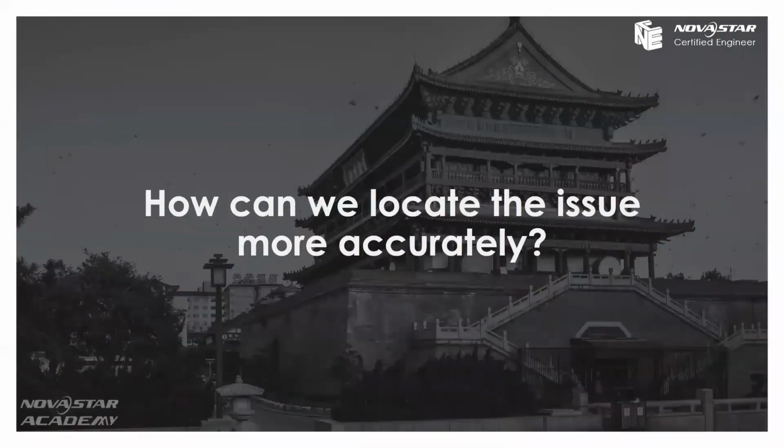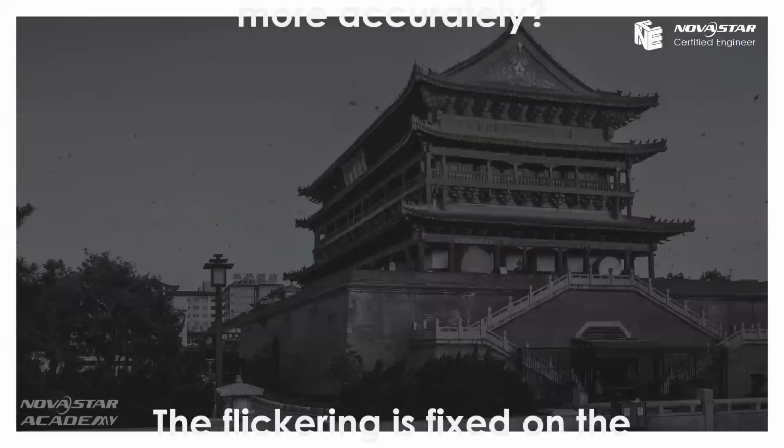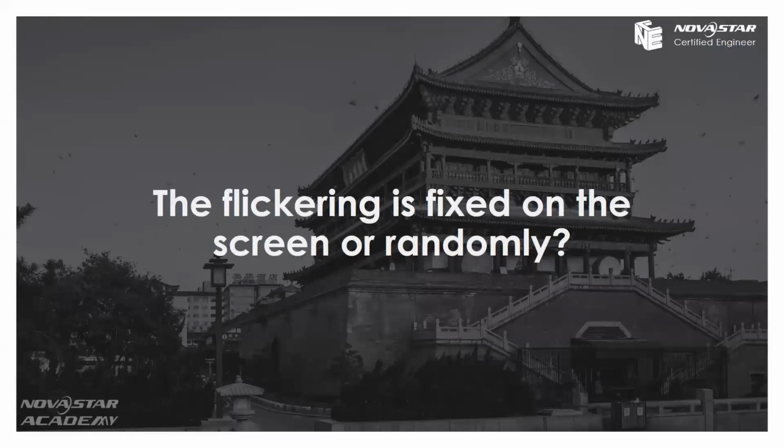the issue more accurately? Regarding the screen flickering issue, normally I will ask the customer one question. Because the customer told me, when I was doing phone support or remote support, my screen is flickering. Okay, I will ask him: is the flickering fixed on the screen or random? Because if it's fixed, we may have a way to troubleshoot. If it's random, or if it's a full screen flickering, we may have another way to troubleshoot.